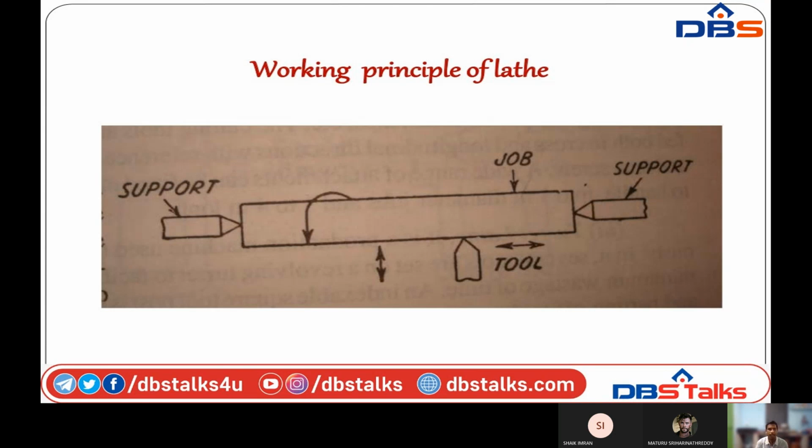We are giving the feed by means of a tool which is placed perpendicular to the workpiece. The main working principle is that the workpiece is revolving or rotating, but the tool is placed at a stationary point. This is the working principle or function of the lathe. Next,